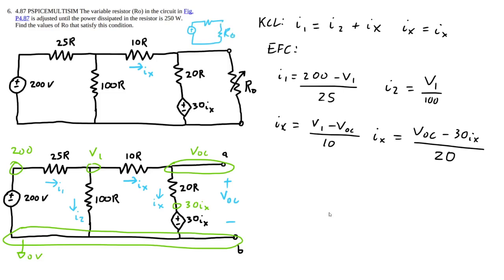So we're going to do a Thevenin equivalent circuit and use that in combination with Ohm's law and the power law, well, not really a law, but the power formula, to calculate what values RO might work for this. So I went ahead and labeled the circuit and wrote down currents and both the equations for components and everything. We're just going to go ahead and start solving.